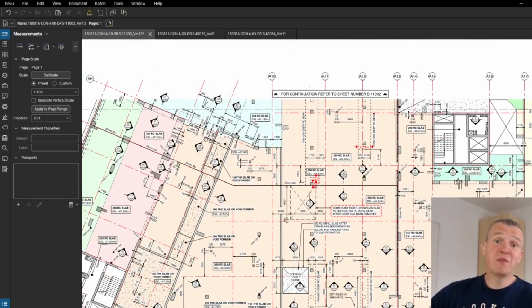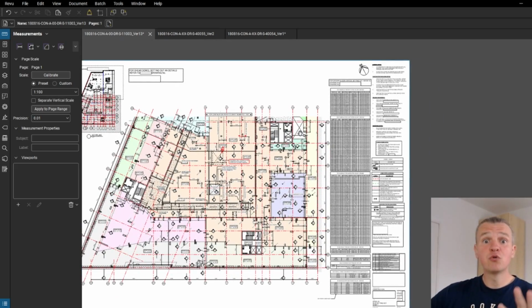So I would say the basic things, guys, are to take the levels and know what the lines mean. Once you've got a dashed line, you know there will be some step or change in the soffit, so you need to be careful with this. And the sections: you need to take information from the sections and make sure you understand the drawing. And obviously go through the legend, make sure you know what the designer means by his symbols.